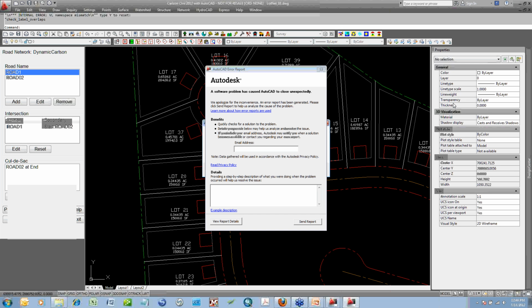So some of your elevations, you'll have to, I don't want to say take them with a grain of salt, but you do have to realize that the elevations that will be shown will be relative to the main run, not necessarily to the existing ground at the point for each lateral. But using the sewer net, you shouldn't have to create a profile for each one if what you're trying to do is to generate your main run profile, showing those locations. I believe that is exactly what you're asking.